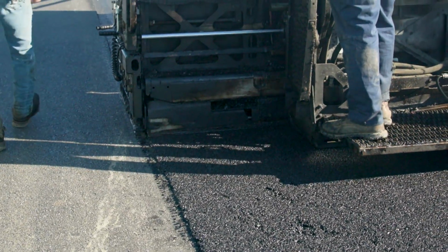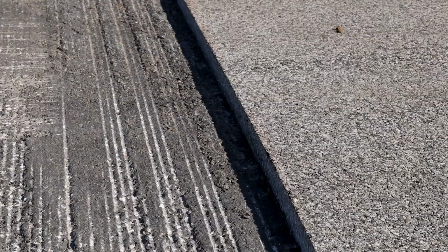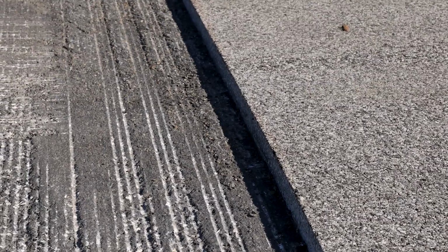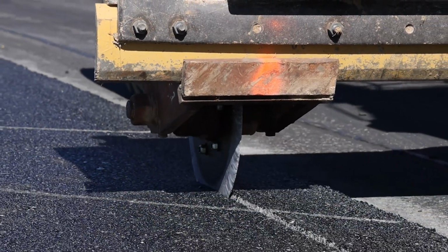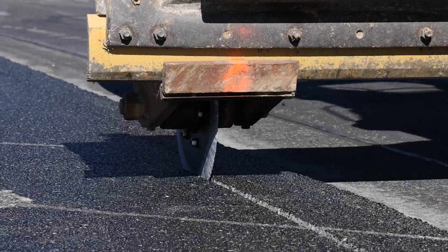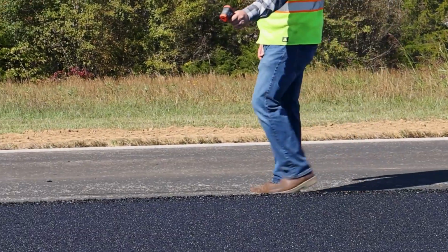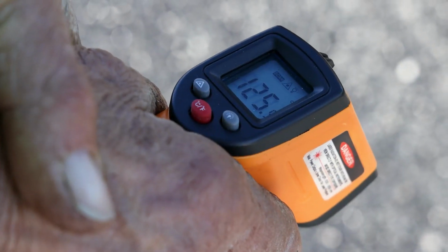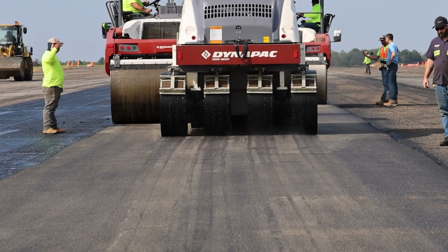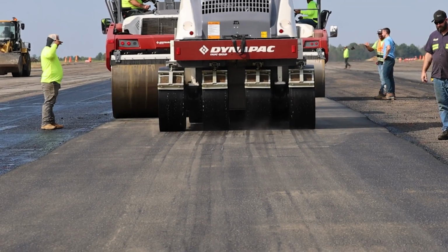Airfield control strips require 2 paving lanes with a longitudinal cold joint between them. The cold joint requires demonstration of cutting back a longitudinal joint. It must consist of an exposed construction joint at least 4 hours old or a mat that is cooled to below 175 degrees Fahrenheit. The lanes must be the same width and depth to be used in production.